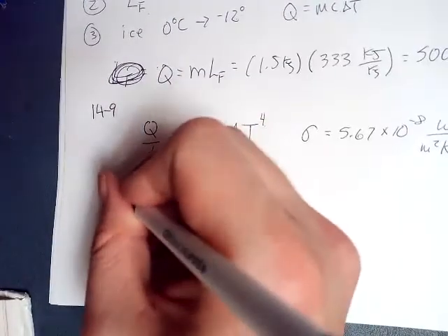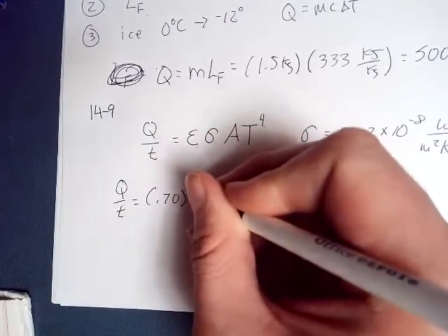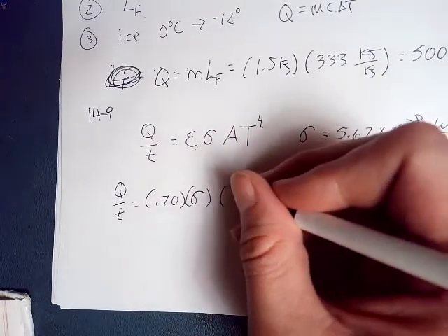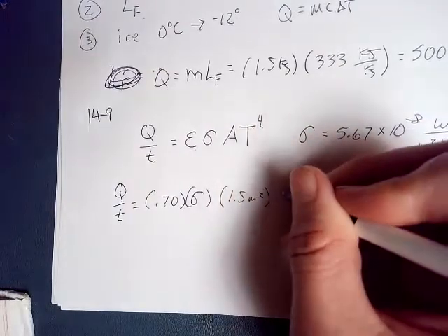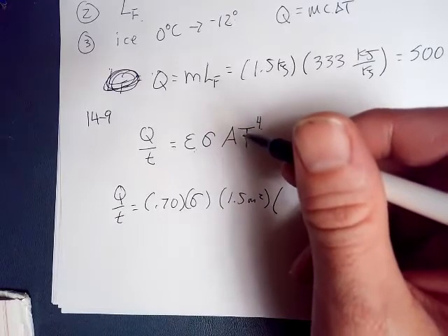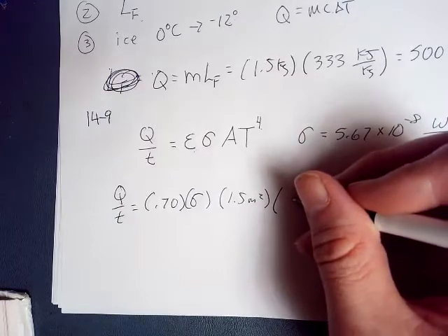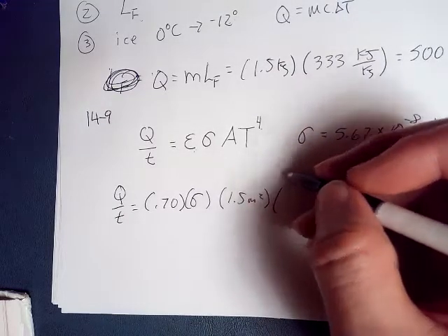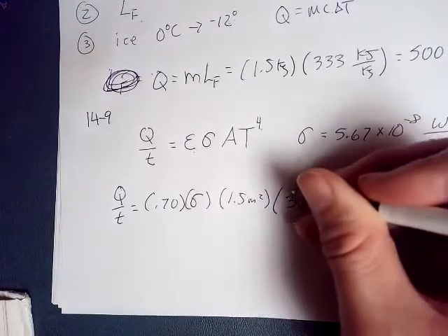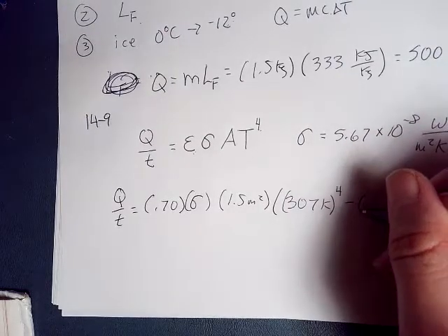So this is just a straightforward calculation. We have the emissivity, 0.7. I'm not going to write that out again. That's the constant right there. The area of the body. And then this T is kind of like a delta T, so you have to treat the temperatures in Kelvin. So I'm just going to go ahead and use those, minus, since the body and this is the wall.